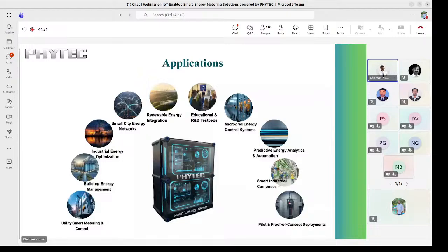And if the active power is greater than, suppose, 400 watt, it will turn off the load also. From the load side, if the power you are using exceeds this specified level, the active power is greater than that, then it will turn off the load. So those two factors I implemented here as AI. Now if I go for read instantaneous profile, it is reading the profile.